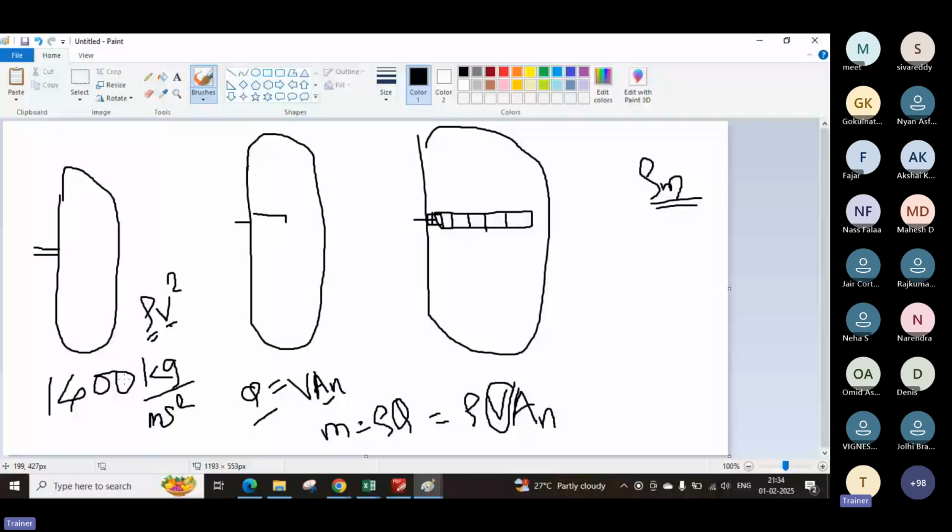If your liquid content is very high and if you want quick separation, then you can use a half open pipe. That has a rho v square value limitation of 2100. This I am telling you from the Shell DEP.